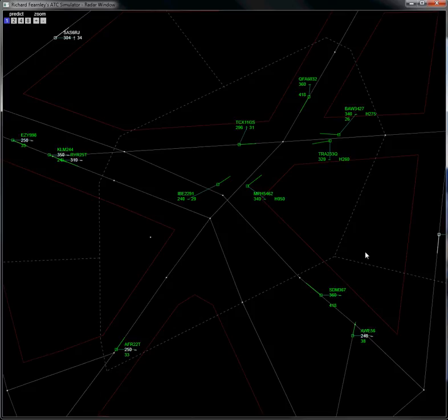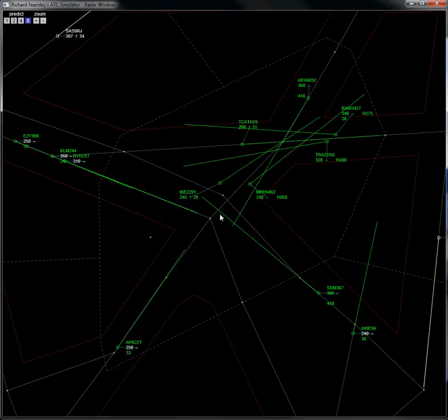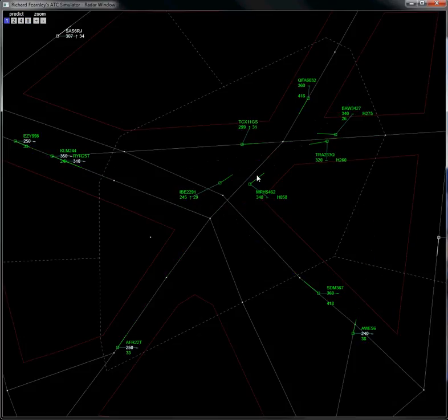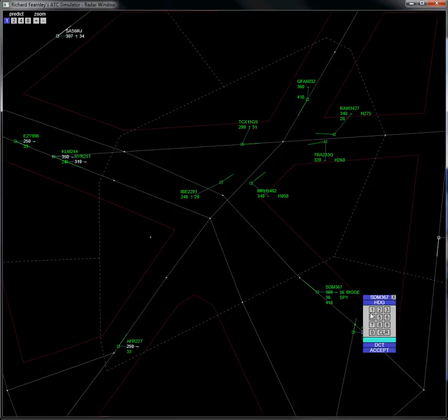Okay, so a new aircraft that's entering my sector. No, sorry, we already planned this one. We said it was in contact with the Qantas 6032. Switch on 8-minute leader lines. We can see we nicely have radar separation if we lock the two aircraft on heading. I'm not really too worried what the heading is, so I just click heading and accept. It puts an H in the label, it locks it on its current heading. I also do this for the Qantas 6032.